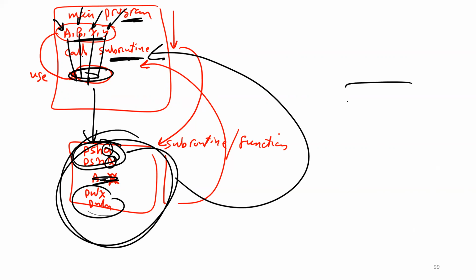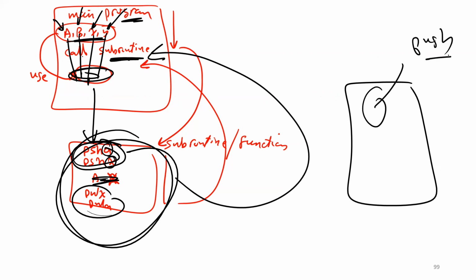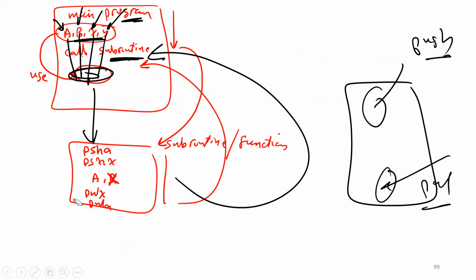If you have a subroutine, guys, all the registers you want to use inside it, just use them. That's totally fine. But you have to push them at the very beginning, and at the very end pull them back. That's what I did here. I'm saying the registers you are going to change; if I don't change a register, you don't need to do that.